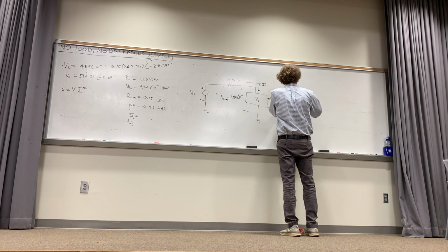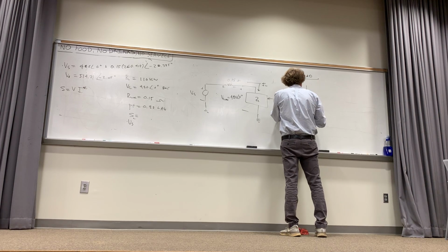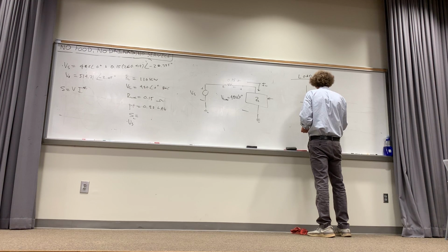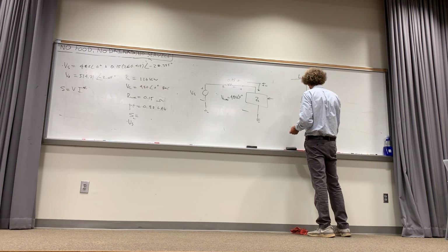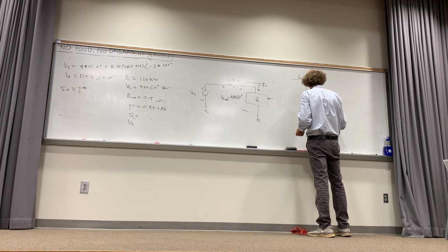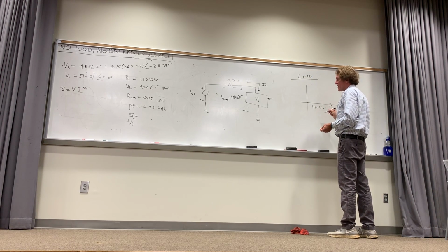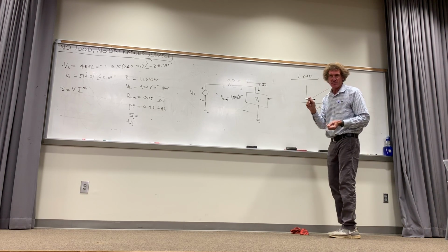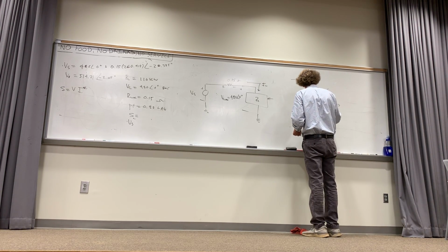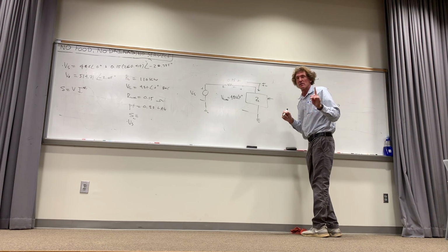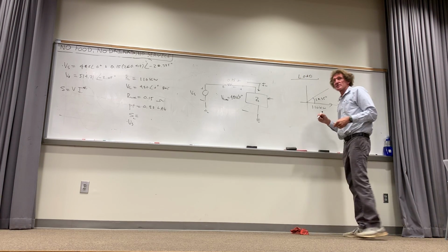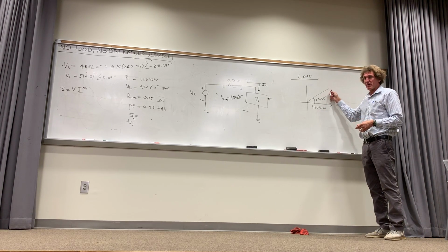This is going to be the load right here. We always put the real power on the horizontal axis, and the real power here was 110 kW. I know I have an angle here of 28 point something degrees. I forgot exactly. 28.35 degrees. And remember, because it's I conjugated, it puts us in the first quadrant when it's lagging.